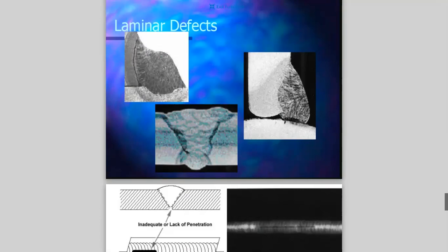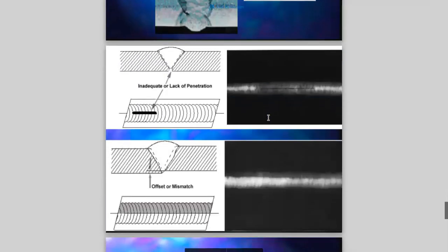All they did is point it at this back wall and lay it in there, and weren't able to get a good bite here. And then obviously we would have liked to have fusion into this as well. If we would have worked on the other side, we would have had more fusion into here, being a nice, solid 100% full penetration weld. Not the case in the picture we just saw. Here, inadequate or lack of penetration.